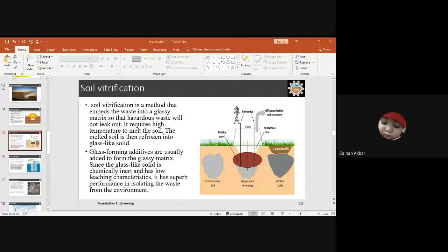The refrigerated coolant extracts heat from the ground, converting the soil pore water to ice, resulting in an extremely strong impermeable material. So this converts the pore water of the soil into solid ice, which increases the stability of the earth and makes it impermeable. It is an environment friendly method. When the wet soil freezes, the water present in the soil is converted to a solid. That turns soil into a solid mass resembling concrete. It gains the strength of concrete.